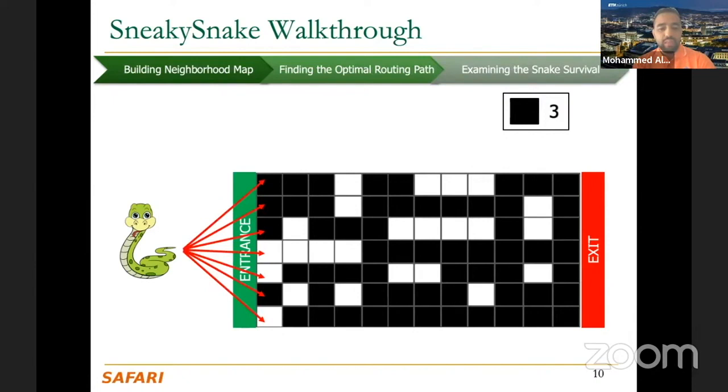It's very similar to the single net routing problem. In each row, you detect how many steps you can go further. So you find here 0 steps because you start with an obstacle or a module, then you cannot pass. Here you can move 4 steps forward because your goal is always to go from left to right. So you want to go as far as possible in each row. That is a greedy choice to get the shortest path. Because if there are no obstacles at all, then you just walk in a single row and that's it.